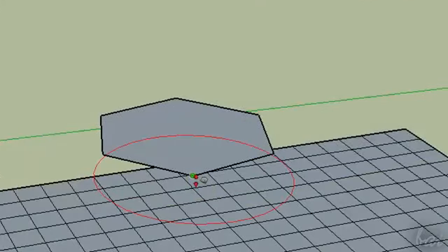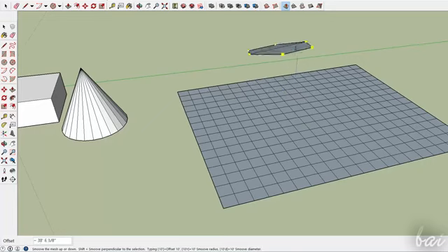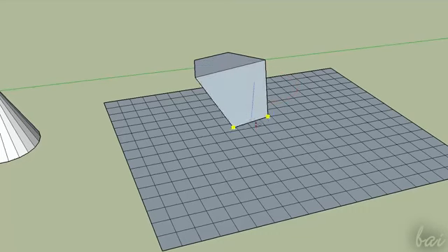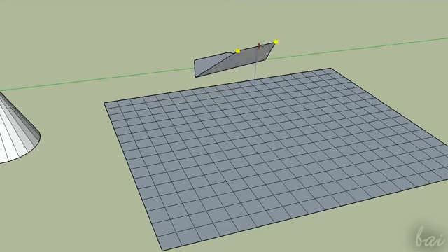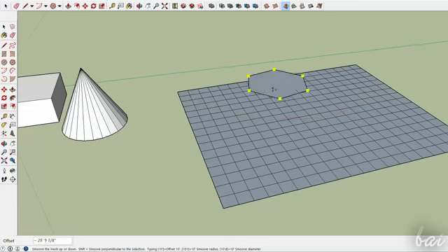The bigger the radius, set as a red circle, the more object sides and/or vertices will be deformed if you drag. All nodes and sides that do not fall inside the red circle won't be moved or deformed. So if you want to move an entire face, click on the face and drag.